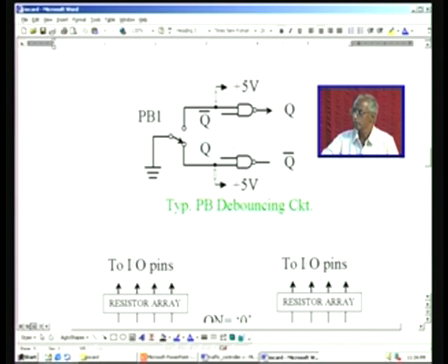And so, to start with, let us see how this circuit works. To start with, this one is 1 because it is pulled high, and this is forced to 0. So, you know that 0 into anything is 0 here. So, just before the bubble of the NAND gate, you get only 0 here, and after the bubble you get 1. So, Q bar is 1 for this particular position of the push button that you have seen here.